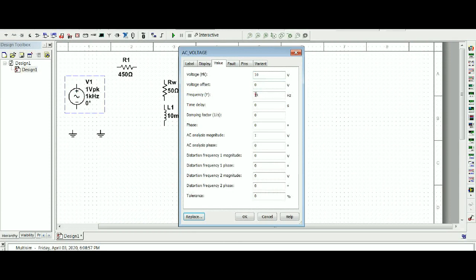At 5 kilohertz, there's this guy. And I'm not only going to look at this from the standpoint of figuring out the phase and magnitude of the output at a given frequency, but I'm also wanting to sweep it. That is, take your hand on a function generator and run the frequency up and down and see what its frequency response signature looks like.